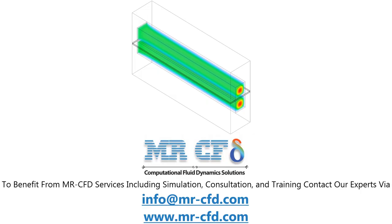The gaseous diffusion zone comprises a porous medium with a porosity coefficient of 0.5 and contains the mass sources: thermal energy, electrical potential, saturated water, and hydrogen, oxygen, and water gaseous species. The polymer membrane region also consists of a porous medium with a porosity coefficient of 0.5 and has thermal energy sources and proton potentials. Also, since the water content within the model must be 0, a fixed value is used to define the value of water equal to 0.